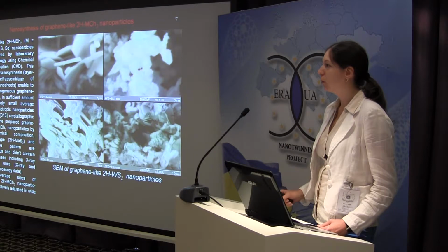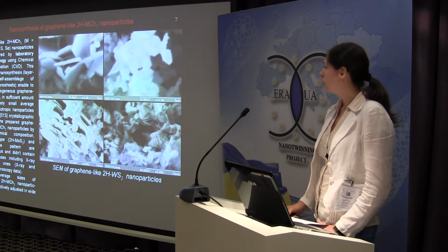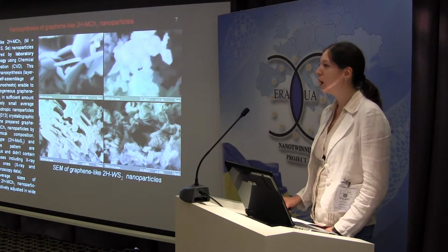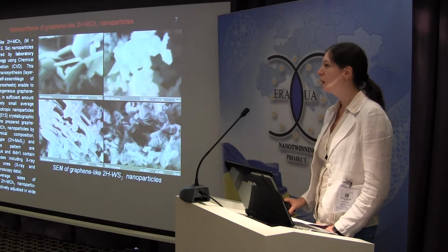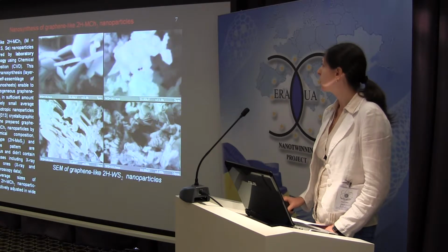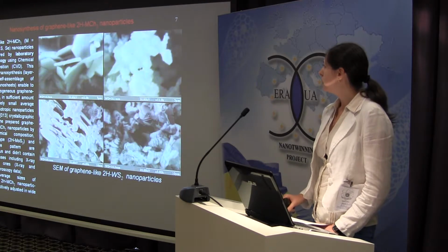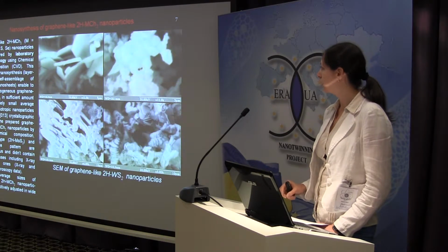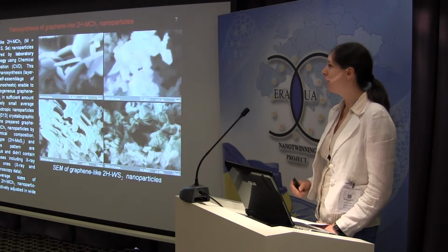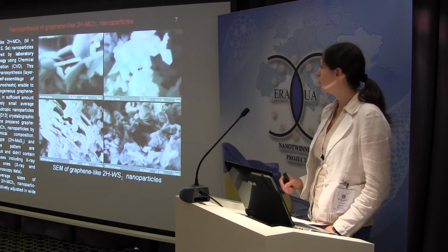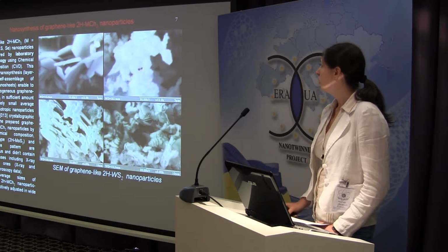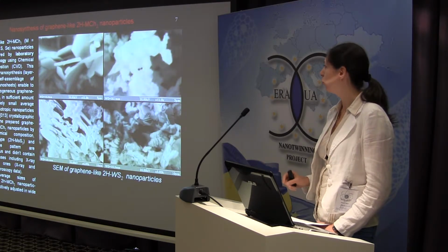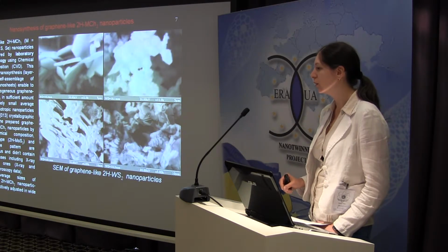We take graphene-like nanoparticles. Graphene-like nanoparticles of molybdenum and tungsten dichalcogenides were prepared by laboratory nanotechnology using chemical vapor deposition, CVD. This bottom-up nanosynthesis, or layer-by-layer assemblage of metal chalcogen nanosheets, is able to prepare homogeneous graphene-like nanoparticles in sufficient amount, and they have small average sizes, on the order of 1 nanometer in the crystallographic direction